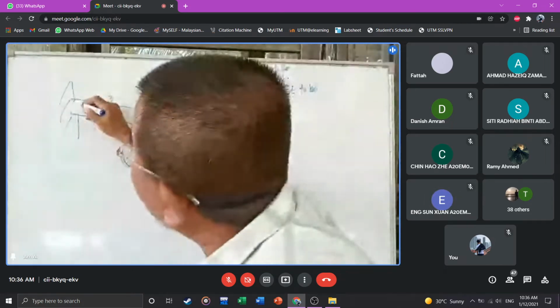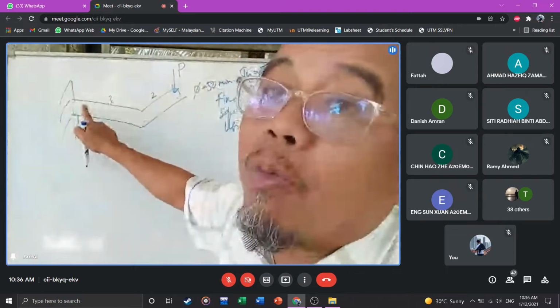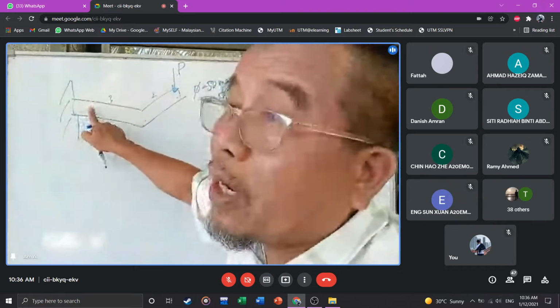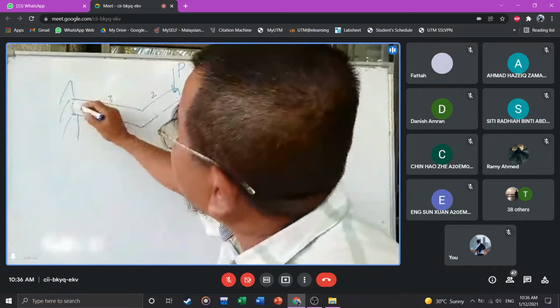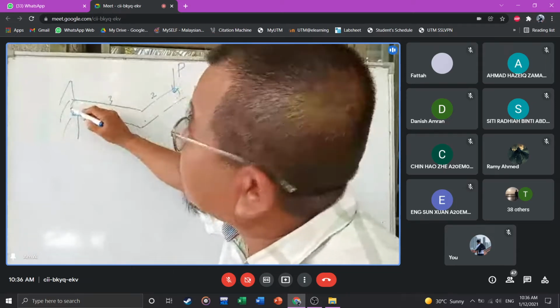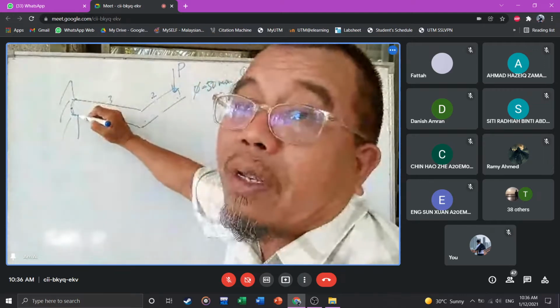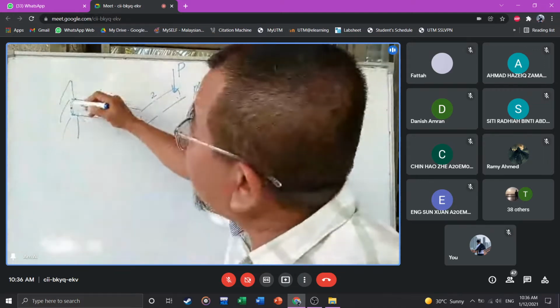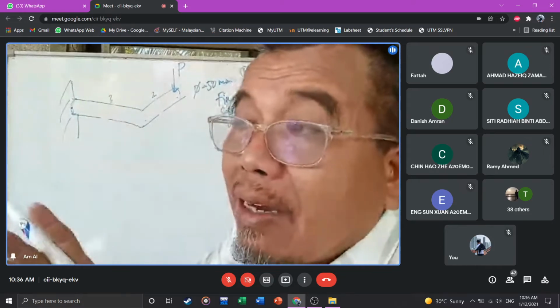And then from here, where is the critical point? Because I have bending moment and torsion, right? So where is the critical point? For bending moment, for this rod here, zero stress there, maximum there, maximum tensile, maximum compression. For torsion, everywhere is the same tau. Can you see that, the reason?